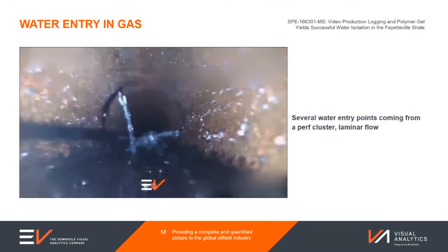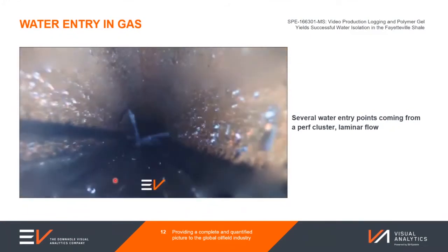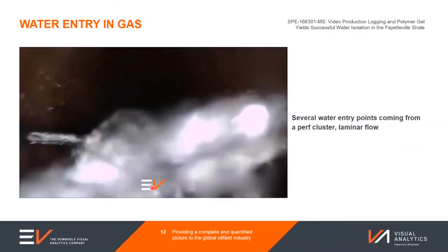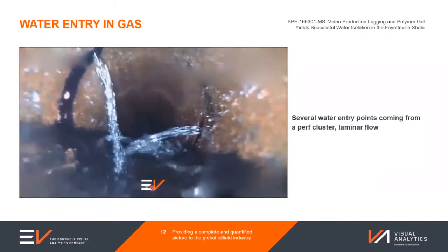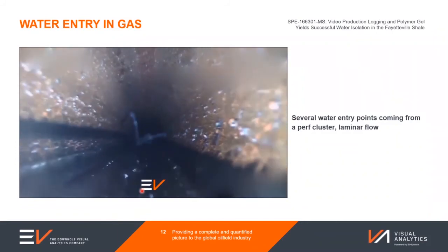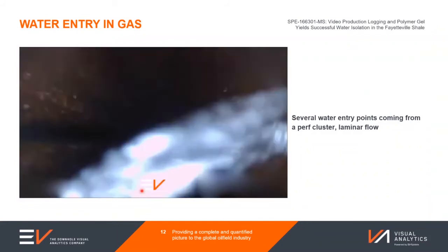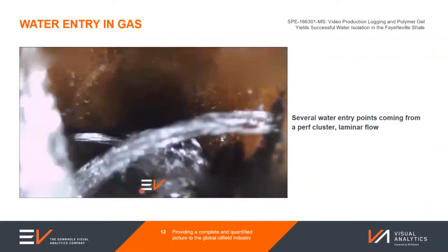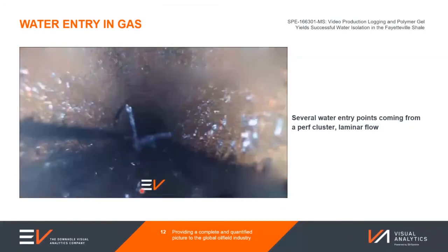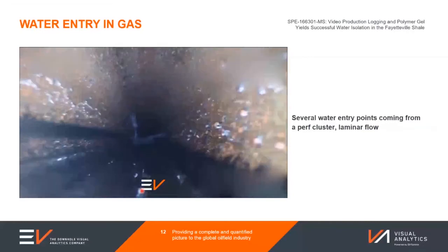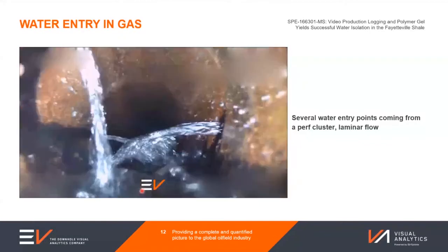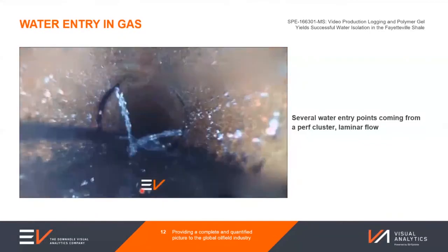So again, the production log may have been able to find some of this flowing water being transported up the well, particularly as we go in and out of changes in inclination. But it would very much struggle to identify the exact location of those perforations because it would probably only have contact for a split second and maybe undersample the result. But by having the two in combination, we could clearly see where the water was, and we can understand potentially its volumes and flow rates from the production log, looking at this in between the stages.